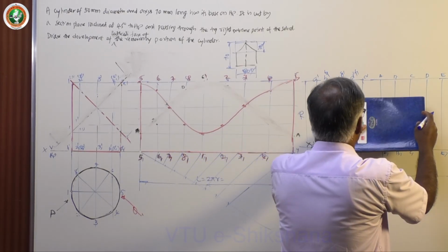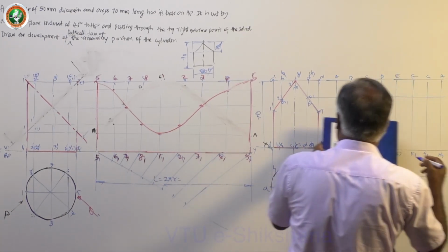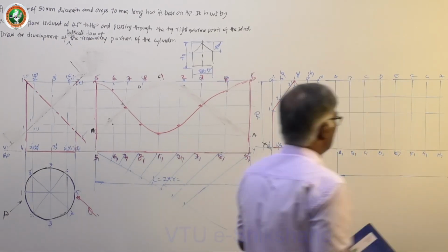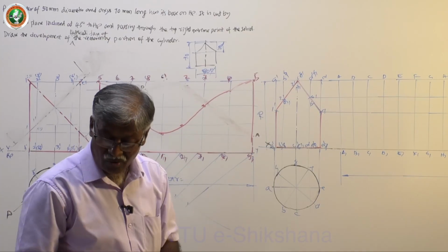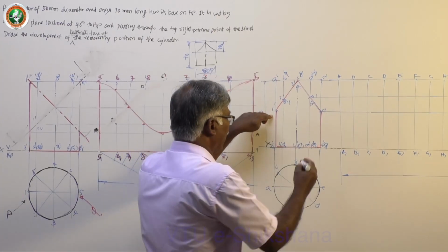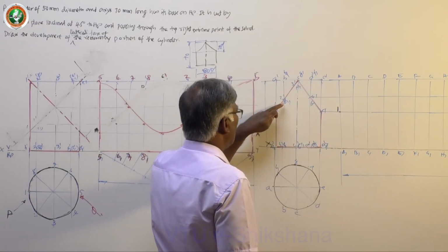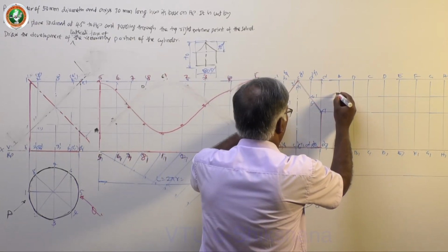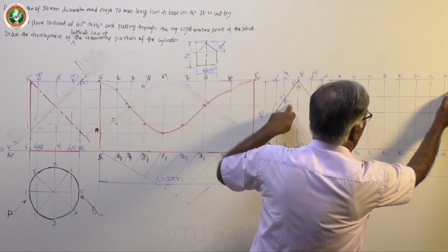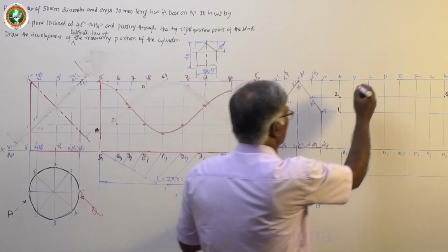Easy. Draw only 3 lines. Already top line is available. It all depends on how many divisions you are going to do. So if you do 12, it will be little more, 2 more extra, that's all. Now be careful in identifying the points of intersection. On A1 we have 1 or 2 points. This is 1. 2 and 8, 2 is on BB1, 8 is on HH1. And 3 is topmost point, at the same time 7 is also topmost point.